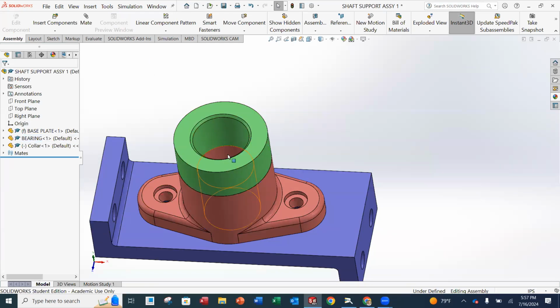But this one, there was only one axis going down. And so even though I can't move this up and down anymore, I can rotate it. And that's what it's missing as far as fully defined. Could you change that? Sure. Do you need to? No. How could you change it? If it's like, I don't want the minus sign there, I want it to be fully defined. This is not required on a circular part, but I'll show you how you can do that.